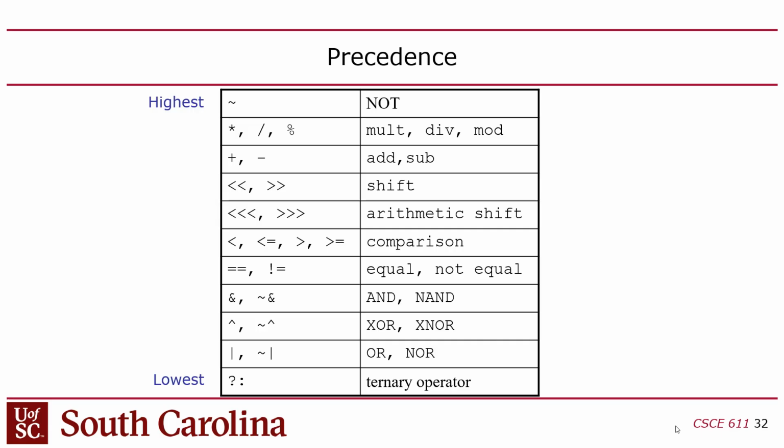Because if you have a comparator in hardware and you give it an undefined value, you're going to get an undefined output. However, if you're writing a test bench, which is not meant to be synthesized, it's meant to just be run as software essentially, like the test bench I showed you, then you can use the equals equals equals, which is capable of comparing two undefined values. If they're both undefined, it'll evaluate to true. In other words, x equals x, whereas in hardware, x equals x is unknown because everything's unknown, right? You guys with me? So you might see that.